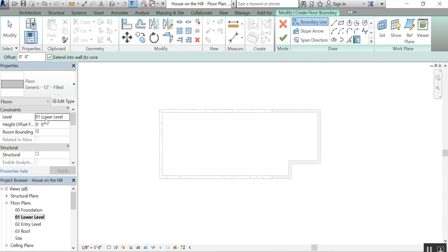It's almost like the top surface of the floor serves the same purpose as a location line in a wall. It's the one constant in this part that will remain unchanged regardless of if we go with a thinner floor or a thicker floor at some future point in time. So just remember, whenever you put in floors, the top walking surface of the floor will, unless told otherwise, always be even or in line with the floor level itself. So I don't think we need to set any other parameters here. I'm just looking really quickly. Nope.